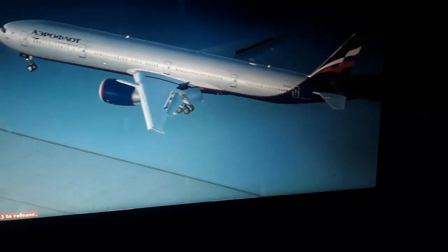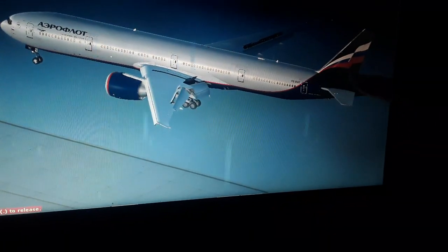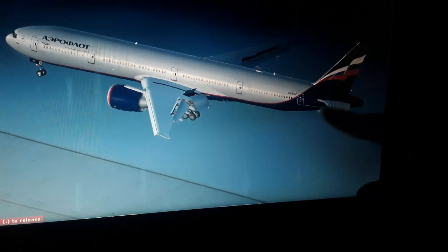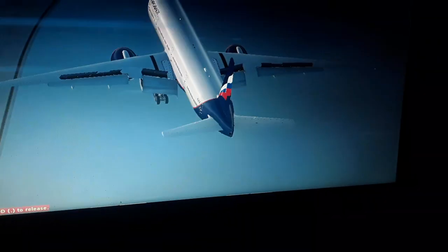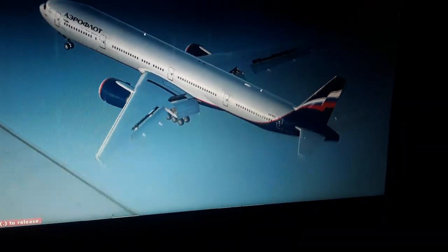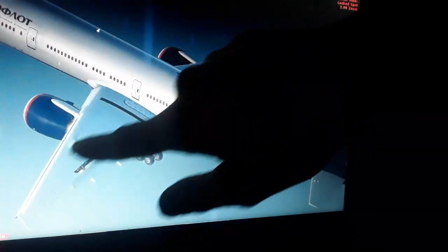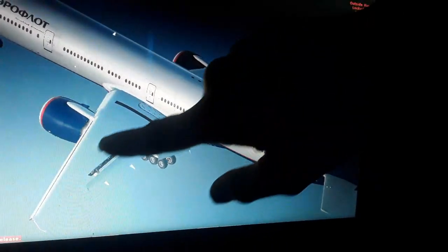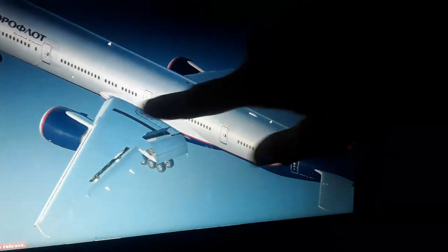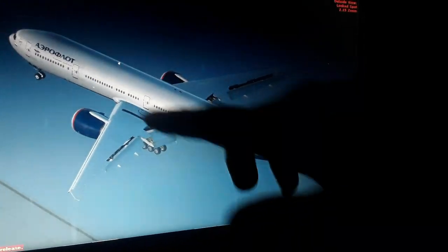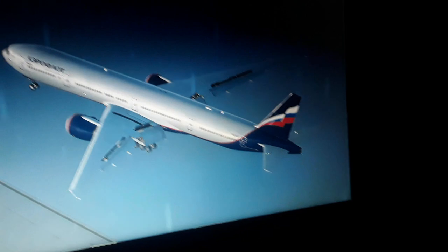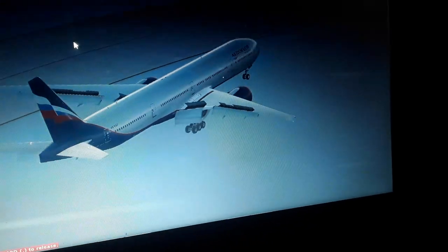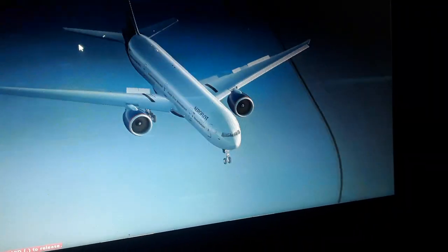that traverses also the center of gravity and the horizontal tail and the vertical tail stabilizer. So we have the mean aerodynamic chord position here, 25% of the MAC in the wings. It's the position where the maximum aerodynamic lift force is being produced, and also where the stall of the wings begins, where the airflow becomes detached from the wings and the aircraft starts to fall, to lose its lift.